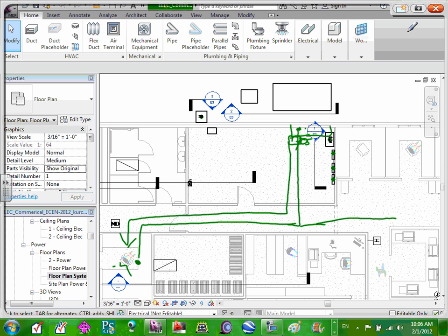If that happens, you want to know that happens, especially if somebody comes in to do work on your fire protection system and shuts the gate valve and leaves it shut, then you want your fire alarm system to know that gate valve is shut, because all of a sudden, if there's a fire, the water can't flow to the sprinkler heads. So a tamper switch tells the fire alarm panel that those gate valves are shut, so water cannot flow to the sprinkler heads. So we asked for 2 of those. 2 tamper switches and 1 flow switch.